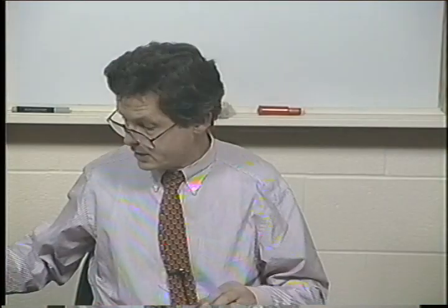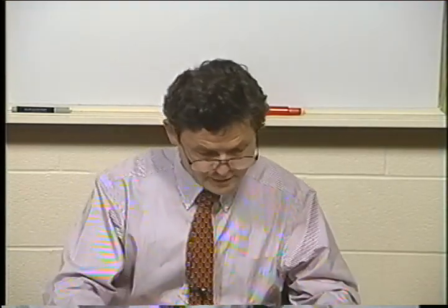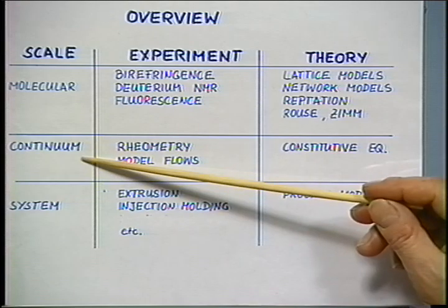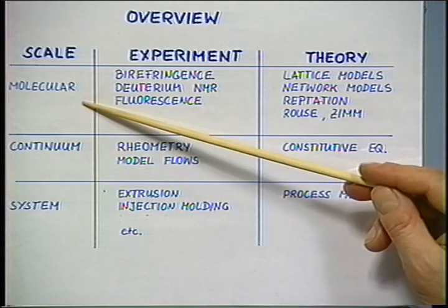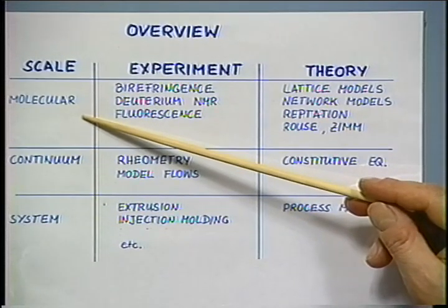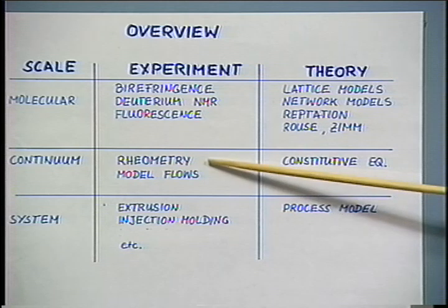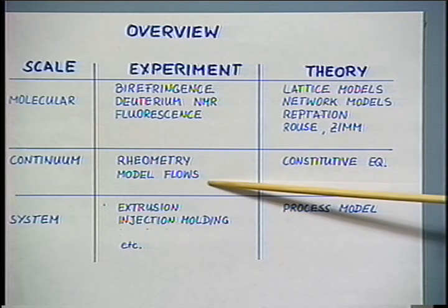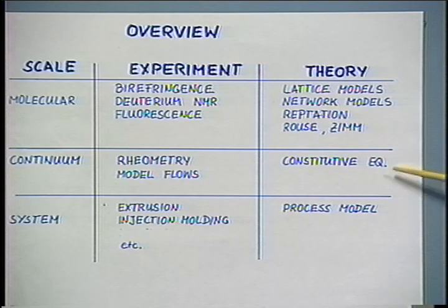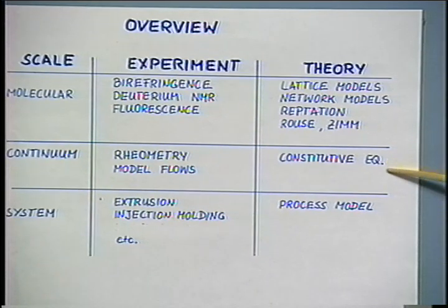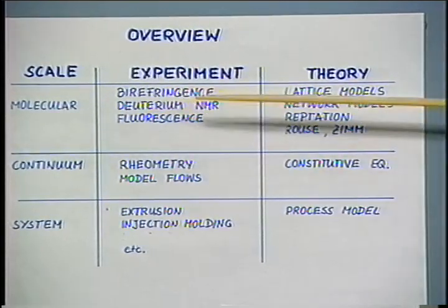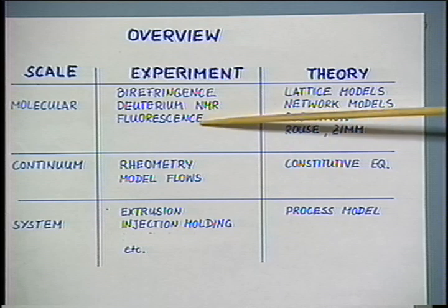So rheology is a tool for us to look at those materials in greater detail. All the course will be on the continuum level. Sometimes we will talk about molecular arguments, molecular explanations of certain phenomena, but it's basically a continuum mechanics course where we use continuum tools like rheometry and modeling of flows. And the theory on this level is concerned about the equation for the stress, the constitutive equation, which relates stress with strain histories.